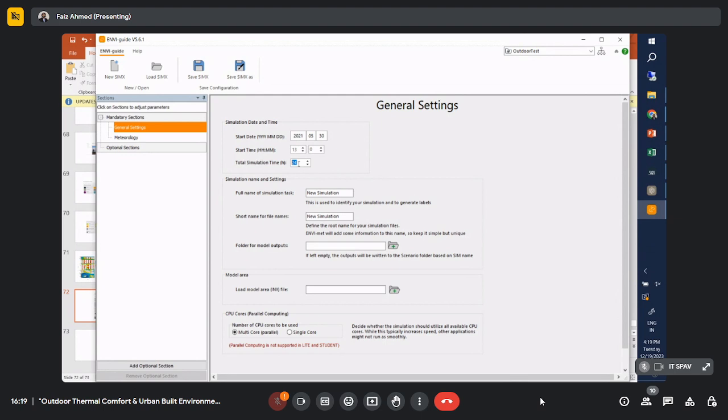Because the settling time of the simulation is like preparing for cooking. In the initial stages, there will be some slow application of forcing, till it takes a few seconds and a few minutes to achieve the actual forcing. So generally, if your results are dependent on only 1 hour, my suggestion is to simulate for 3 hours, so that you have some results in the beginning and some results afterwards also.